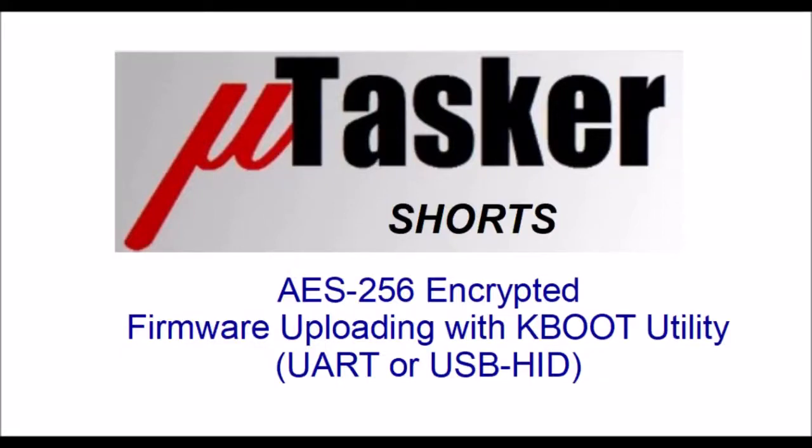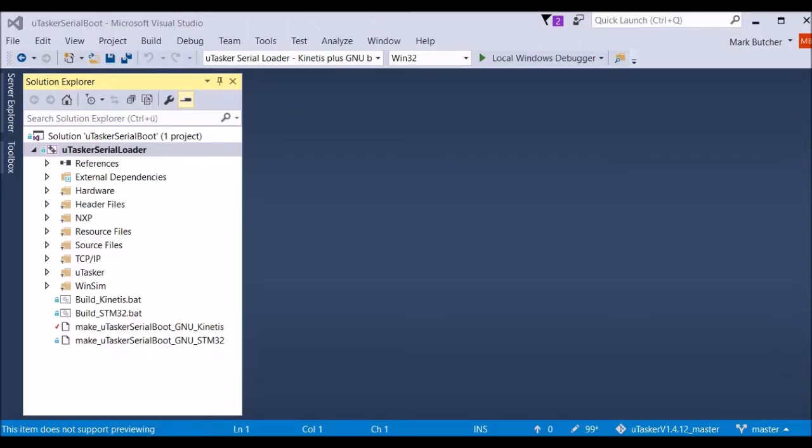Hello and welcome to this MicroTasker Shorts video where I'll be showing you how to build a KBOOT compatible bootloader with AES256 encryption. This operates on either the UART or the USB-HID interface and can be built for almost any Kinetis part. Now I'm building in Visual Studio with a post-build GCC makefile step. The project, however, can also be built with KDS, MCUXpresso, IAR, Keil and various others.